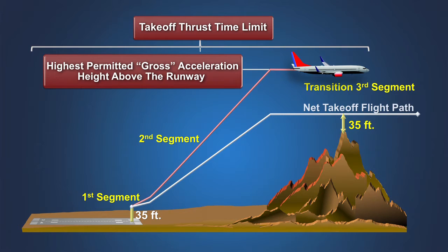For those runways where obstacle clearance is not a limitation, the operator often establishes a standard acceleration height, for example, 1,000 feet above the runway elevation. The acceleration height is provided on the airport analysis for each runway end. Leveling at this height may be required for obstacle clearance in one of the takeoff flight path segments.